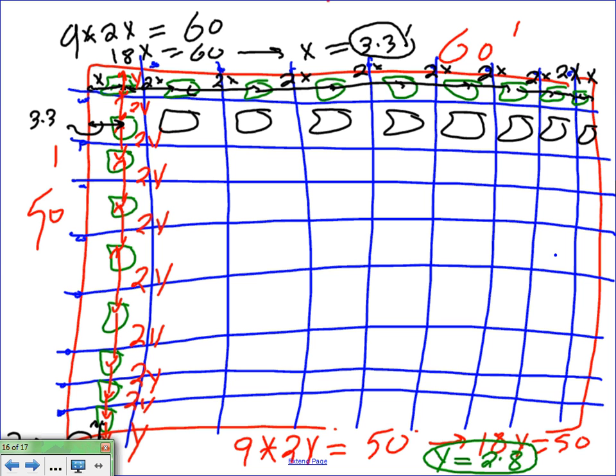In 2008, I think, or 2005? Now I'm confused. Somewhere in the last two cycles, they got rid of this. Now it doesn't matter if it's lighting and small appliances or power panel, it's a panel. And is there any limitation of 42 circuit breakers anymore in the code? No, no limitation. There are some exceptions, one or two, but no limitation for the most part.